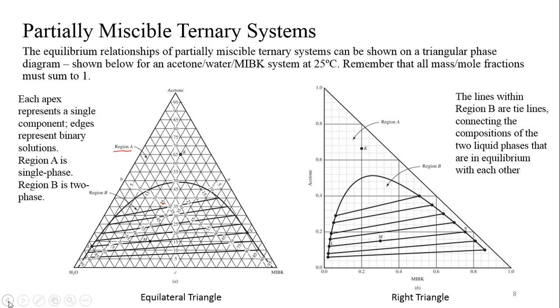If we use the equilateral diagram here, we know that we are at 5% acetone. We also know that we are at an equilibrium situation with two phases in equilibrium, which means we have to be on this two-phase envelope someplace. So we can come over here to where the 5 weight percent is, and then read off the composition of that particular stream.